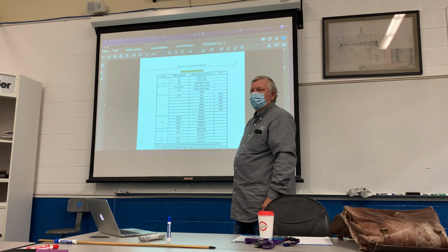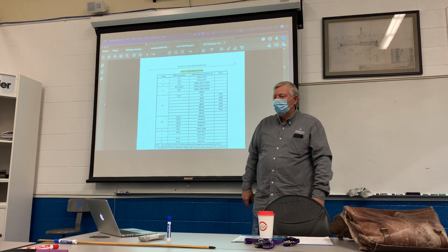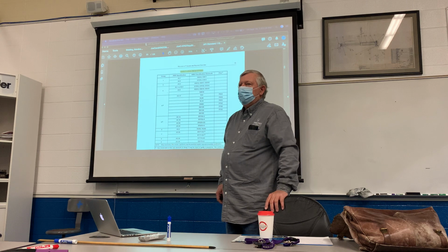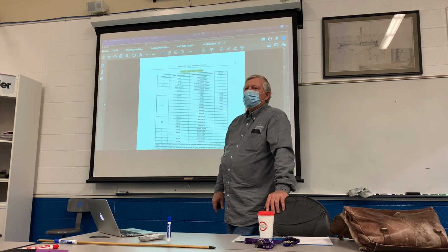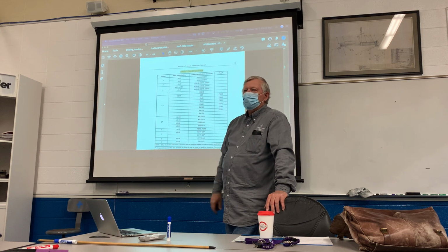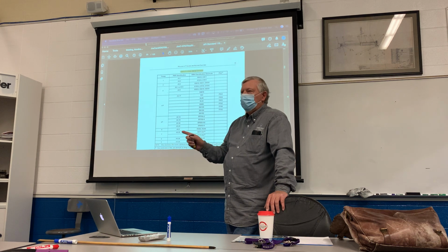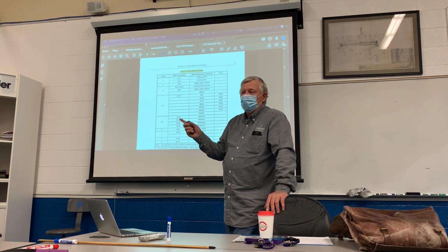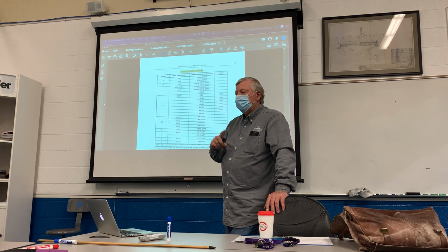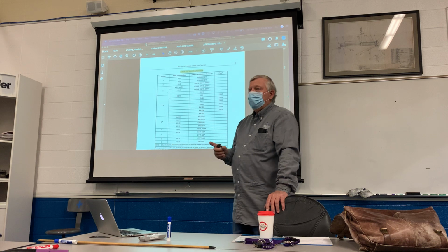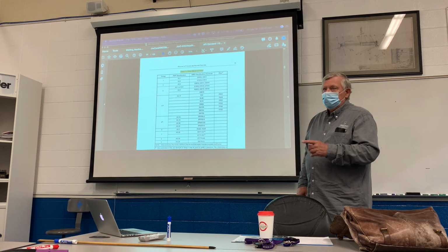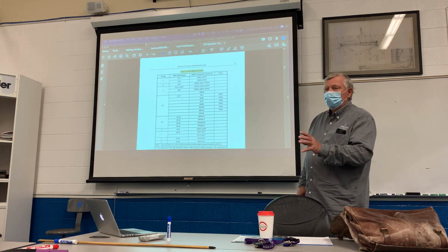For what? It still has to be preheated before you make the weld. No. Procedure says to preheat to 275, so we're preheating all that pipe, so we can just go ahead and weld. You're slowing us down with this preheat. No. Okay. But a welder could go on there, and if your procedure says 300 degree preheat Fahrenheit, plus or minus 20 degrees, plus or minus 50 degrees, he could adjust that down to 250, as long as it's 250 when he starts welding.